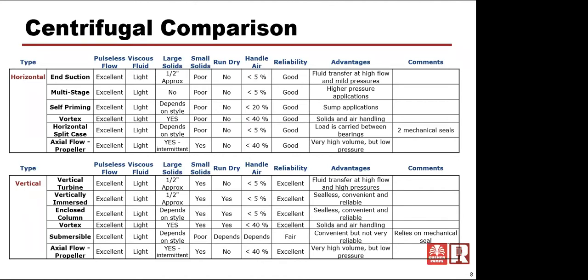It can handle, in certain cases, pretty viscous liquids, nothing like some of the positive displacements can, but light viscosities. Generally, a lot of these can handle very large solids. Some of them are quite poor in being able to handle solids. Some of them are built to be able to run dry, such as some of the vertical sealless pumps that we do a lot of. Some of them can handle large amounts of air, such as a vortex pump or a recessed impeller pump.